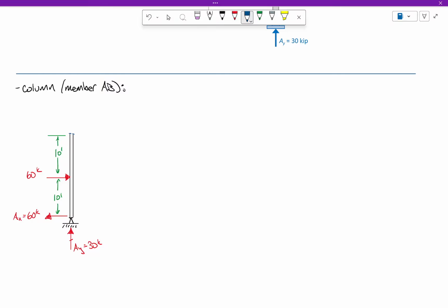No, it's not. Because, for example, I have 30 kips going up. That has to be balanced by something. Otherwise, this is just going to shoot into space, right? So it's not in equilibrium. So what's going on? Well, it's the same thing that's going on when we cut a section with beams. If I'm sitting on this beam, and Mr. Fry takes out the lightsaber and cuts through the table right here, I'm falling to the ground, okay? Because the table right here was containing internal forces that kept the structure in equilibrium. Let's figure out what those are, okay?